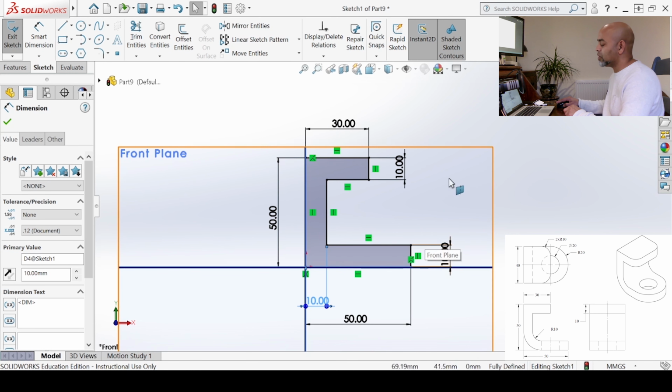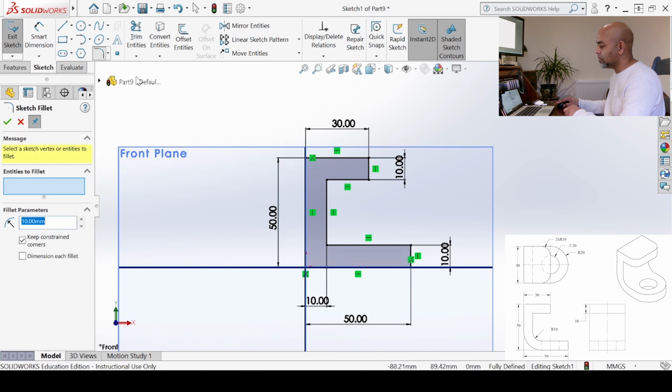I'm happy with that. Whilst we are on the case, I think we need to introduce the fillet around here. It's better to do this in this particular one in the sketch environment. Now, if you observe the fillets, we know the wall thickness is 10mm, and we've been given this fillet radius is 10. So in order to keep it all nice and soft and concentric, I'm going to make it a nice 20 fillet round here and R10 round here. Okay, so let's see if we can get that effect going now. I'm going to blend that in 10mm, like so, like that profile there.